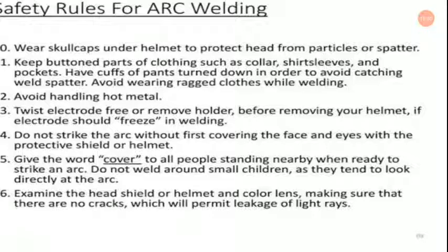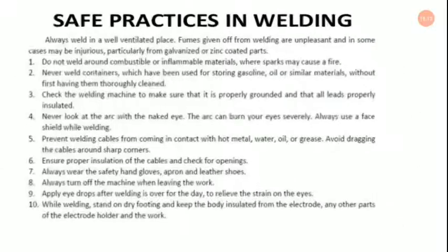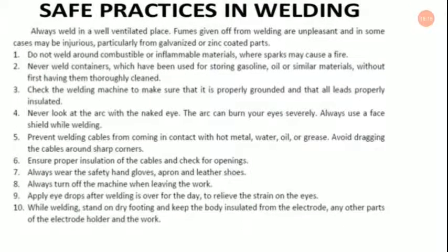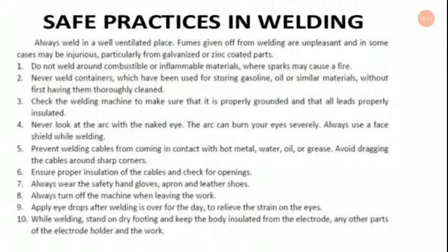Next, you have to examine the head shield or helmet and cover lens, making sure that there are no cracks which will permit leakage of light rays. Now, the safe practices in welding: always weld in a well ventilated place. Fumes given off from welding are unpleasant and in some cases may be injurious, particularly from galvanized or zinc coated parts.